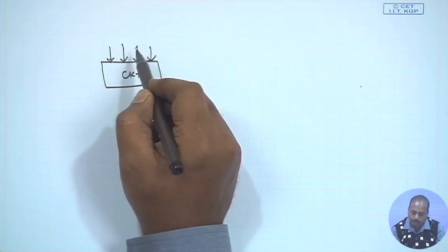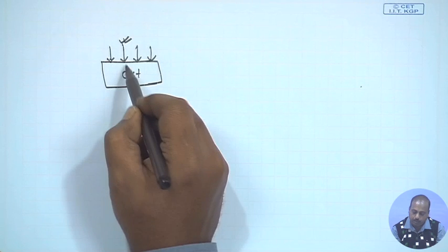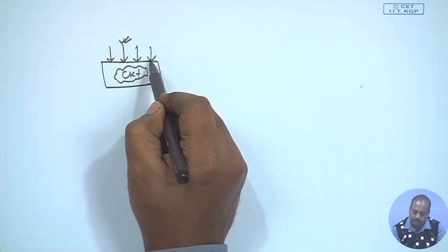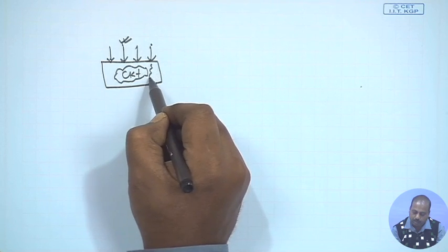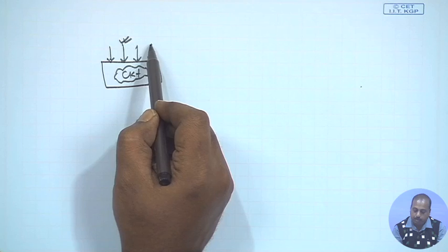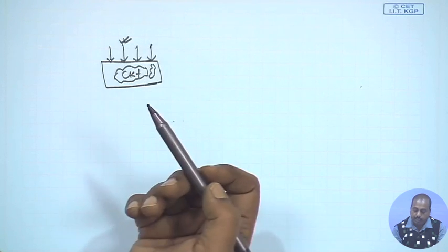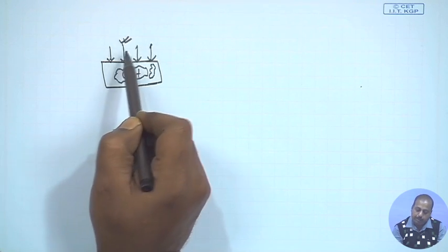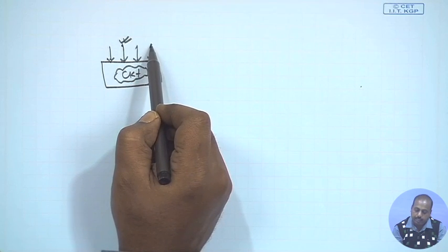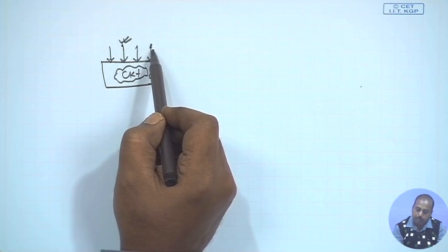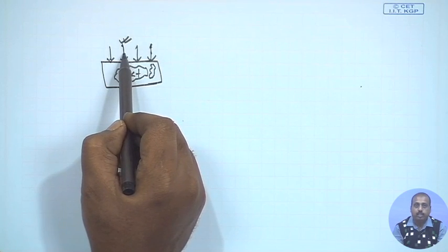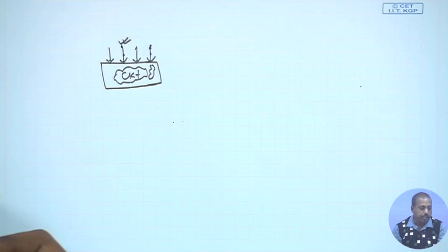Out of these 4 inputs, if you change the value of this input, it affects a larger region of the circuit, whereas if you change this value, it affects only a small part of the circuit. From the power angle, I will be happy if my test patterns do not change this input much but change this other input more. I am ready to have more toggles on this line, but fewer toggles on this line, if the switching is high.